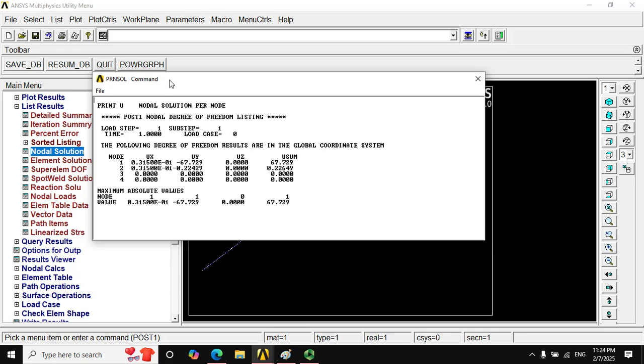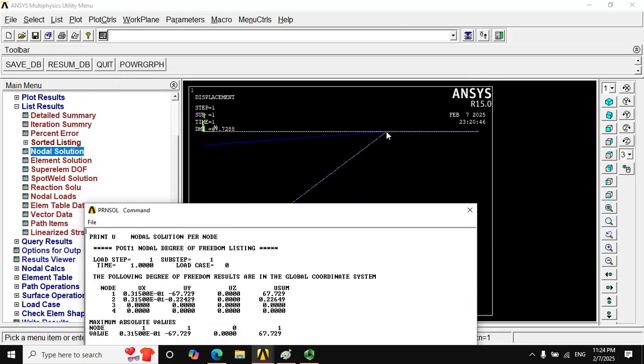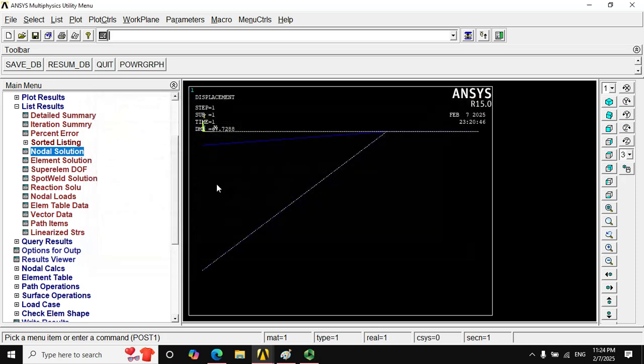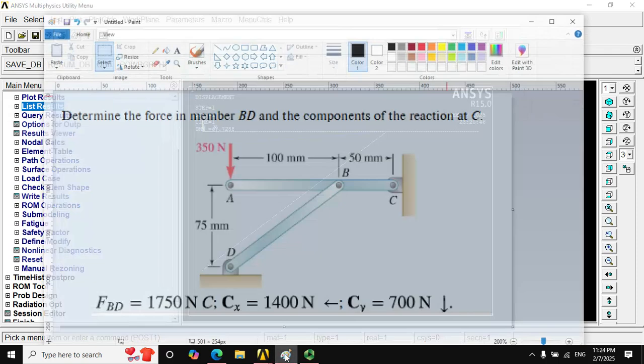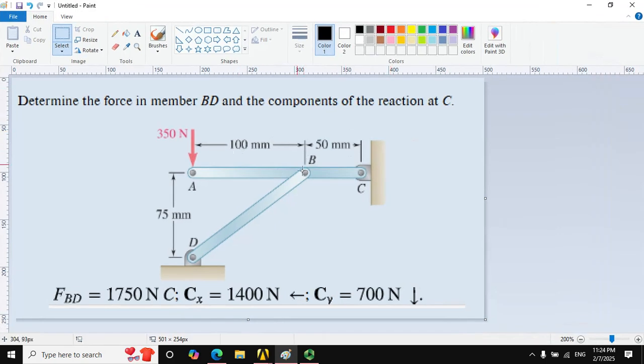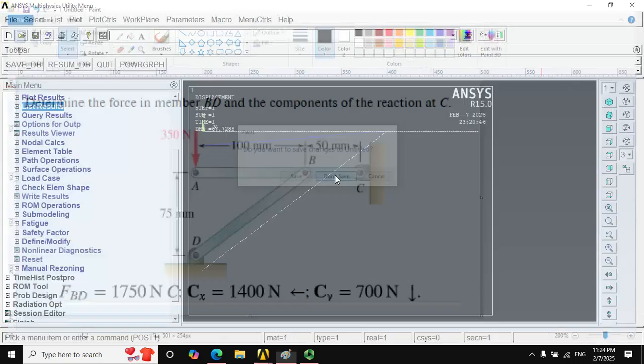And then point 2 is going to move too. Point 2 was here, this guy, where the link element and beam elements are connected. So that's one, we have it. The other ones are 0 because we constrained them. So this shows us how we could model a frame that has both link element and beam elements. And we found reactions, and we were able to find forces and also stresses.